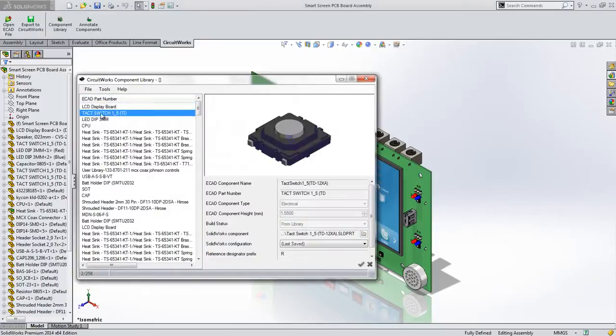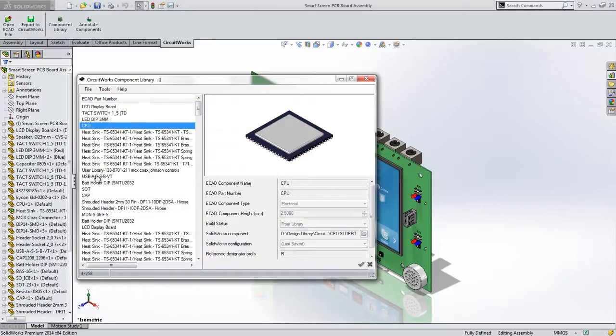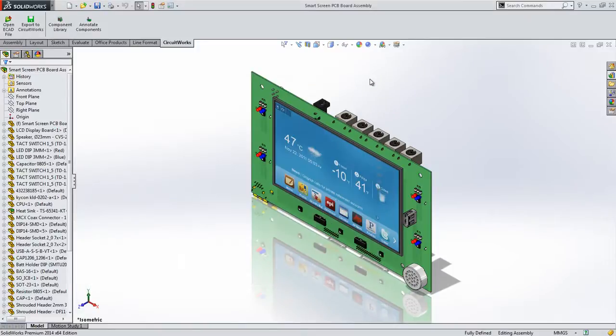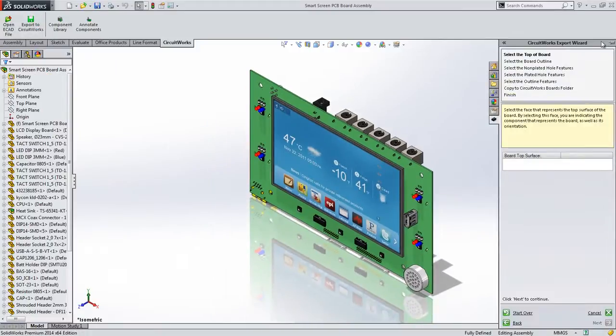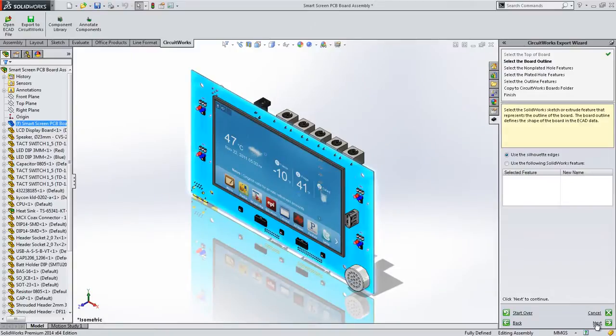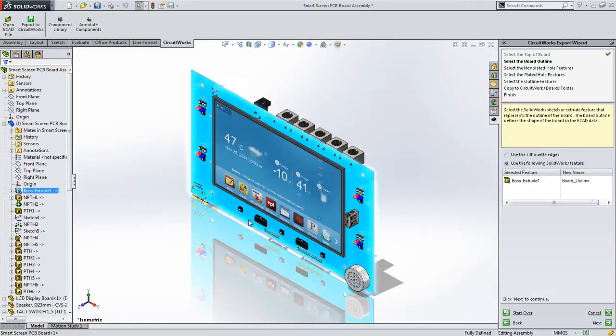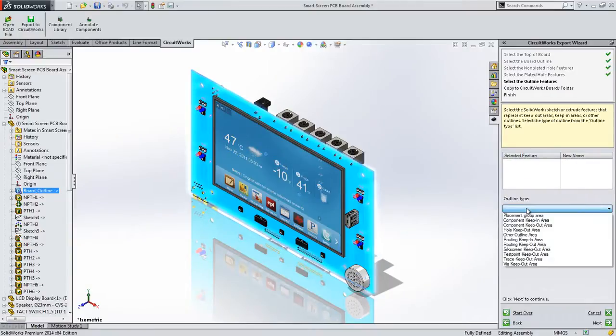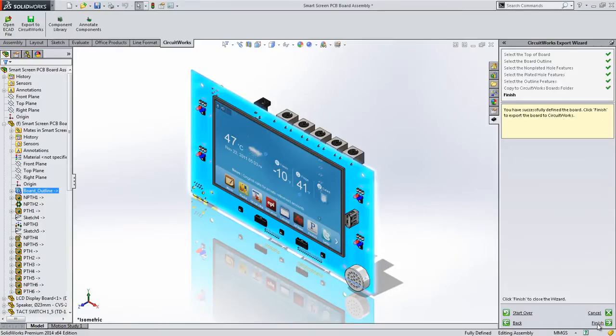SolidWorks' built-in library connects with the 2D electrical engineers' data, meaning that anything we do in 3D can be brought over. We simply need to choose to export it to SolidWorks and follow the guided wizard. In this case, we do need to tell it where the PCB board's main face is and find a few different things, such as do we want to select the outline or let SolidWorks generate it for us? Then we want to find our non-plated holes and our plated holes in our designs. And finally, we can specify any important areas such as keepouts in our designs.